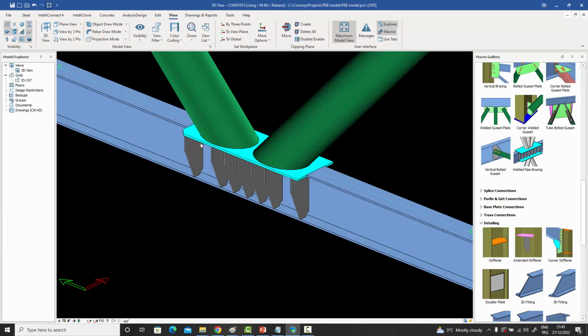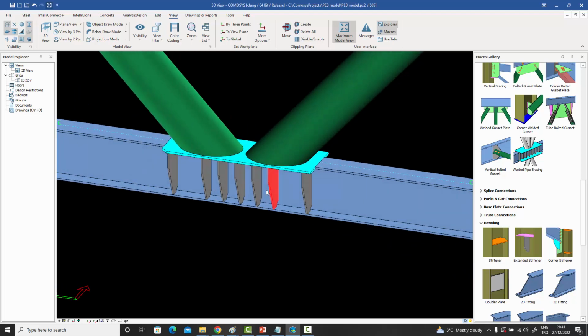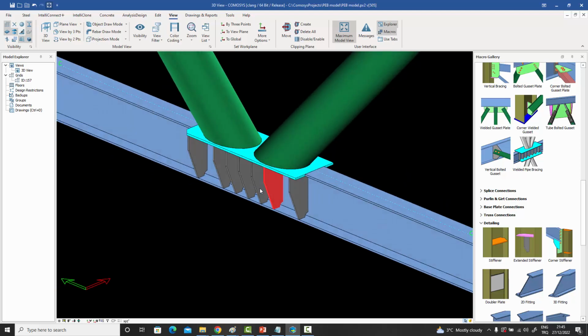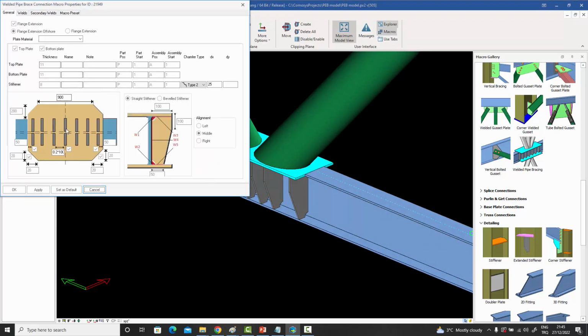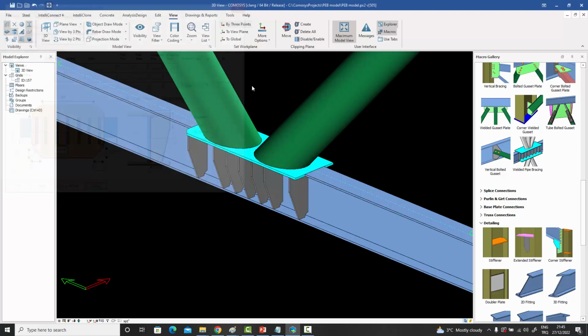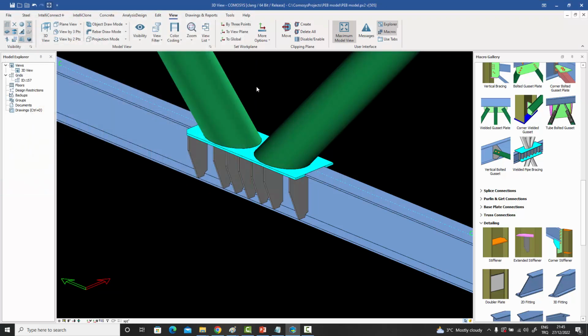The flange has been cut out and a plate has been inserted to widen it, and we have as many stiffeners as we want below. The interface is complete, and we can basically have as many of those plates as we want, and we can give it whatever width that might be needed in the circumstances. But the idea is that you can just directly connect your welded braces to the beam, no matter how wide they are, because it's going to widen the flange anyways.